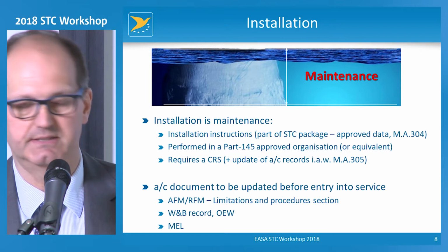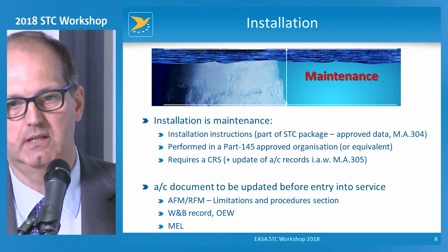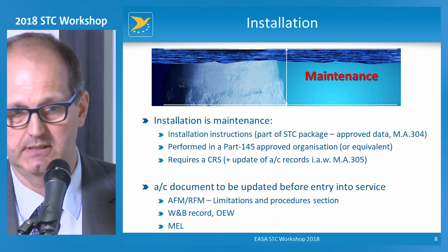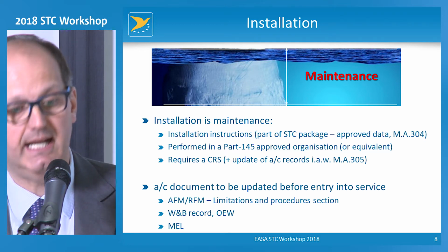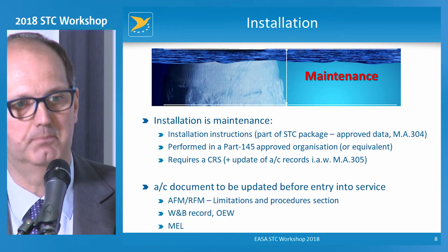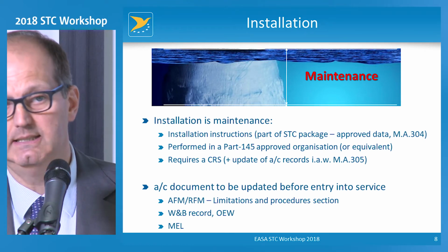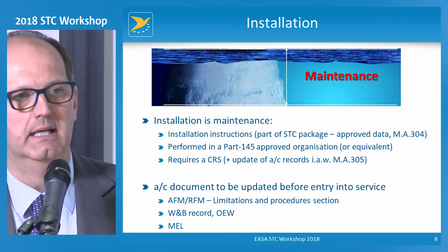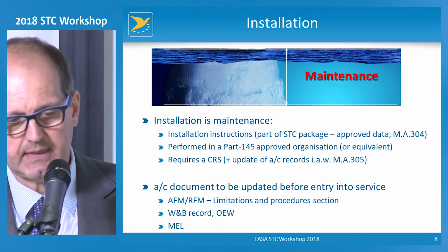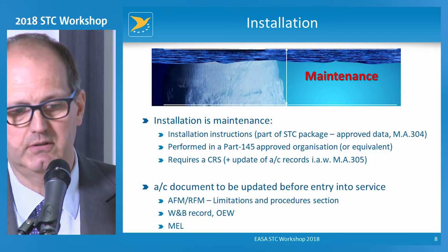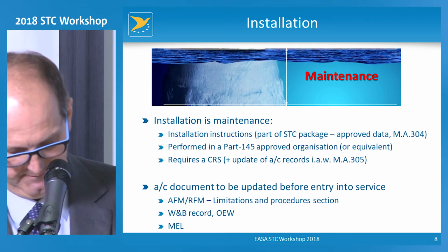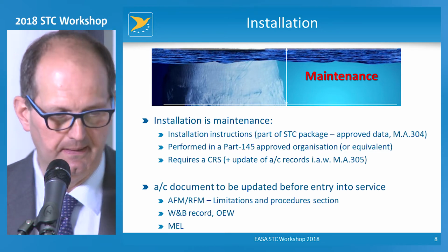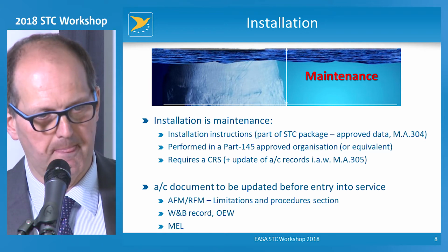In some cases, there are impacts on the weight and ballast records. The change may have an effect on the operational empty weight, and some of the elements maybe are allowed to be unserviceable for a limited point of time, meaning that they have to be reflected in the minimum equipment list.